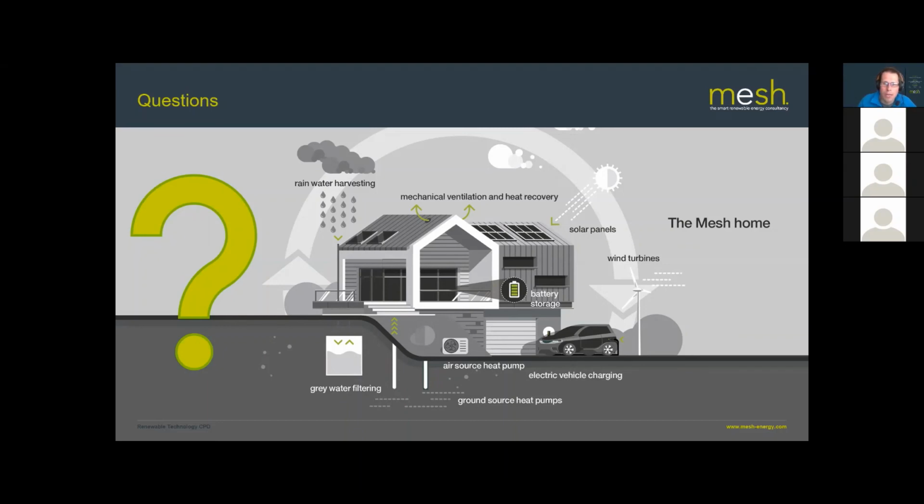How much more would a PVT system be in comparison to PV? Rob, I honestly haven't checked the prices for PVT recently, so I couldn't tell you. But it'd be safe to say that they would be fairly significantly more expensive. And as a general rule, the PV efficiency on PVT systems is lower than for a straight PV panel without the solar thermal element.